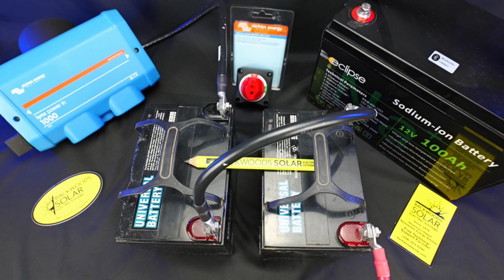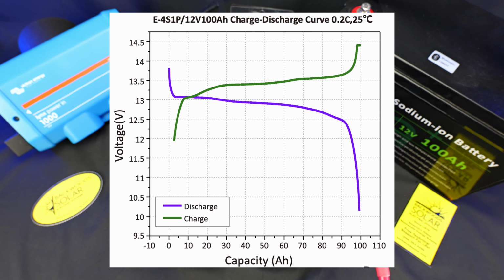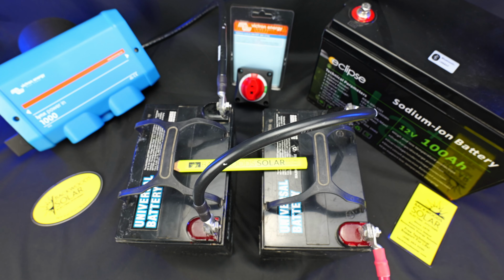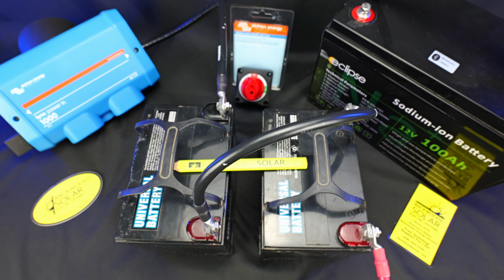And I would say in a lot of cases with lithium or sodium, almost a requirement, in particular with lithium iron phosphate chemistries, due to the fact that lithium iron's discharge voltage characteristics remain exceedingly flat throughout most of its discharge cycle. So it becomes very difficult as the end user to determine based on voltage alone what capacity your battery bank is at. This is where these meters constantly measuring amp hours in, amp hours out, provide a very accurate measure once calibrated of battery bank capacity and overall health.